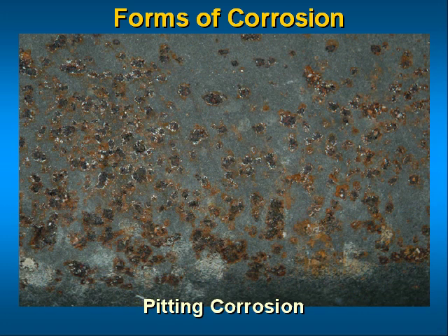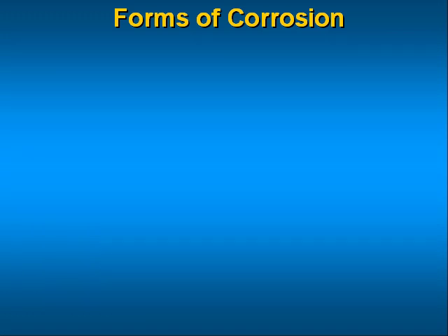Pitting corrosion is localized corrosion that occurs at microscopic defects on the metal surface. The pits are often found underneath surface deposits caused by corrosion product accumulation. The rust bubbles or tubercles on the cast iron indicate that pitting is occurring. Researchers have found that the environment inside the rust bubbles is almost always higher in chlorides and lower in pH, which means it's more acidic than the overall external environment. This leads to concentrated attack inside the pits.